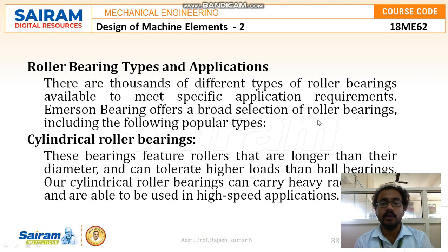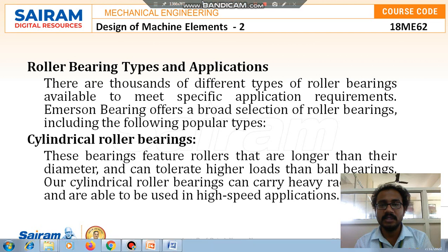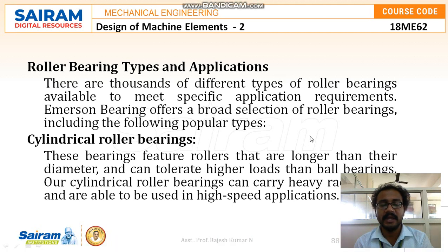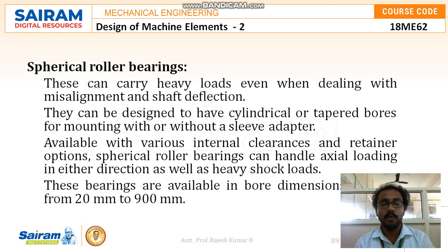Cylindrical roller bearings. These bearings feature rollers that are longer than their diameter and can tolerate higher loads than ball bearings. Our cylindrical roller bearings can carry heavy radial loads and can be used in high speed applications. Moving to the next type, spherical roller bearings.